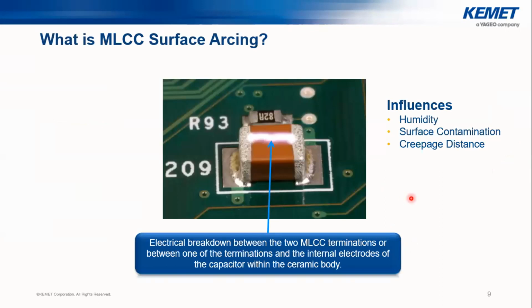When it comes to MLCC, one of the issues is that the trend is going toward smaller and smaller case sizes, but we are limited by the fact that higher voltages may not be possible with smaller MLCC chips, especially in environments with high humidity, high surface contamination, and considering the creepage distance.